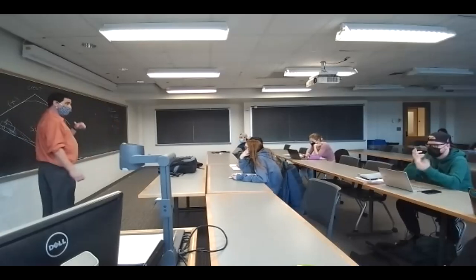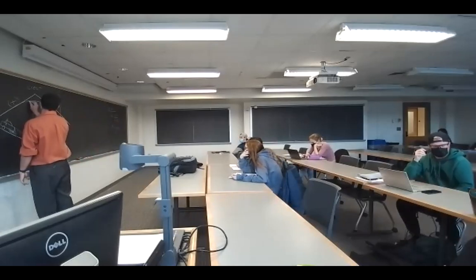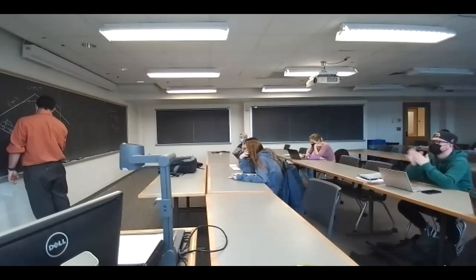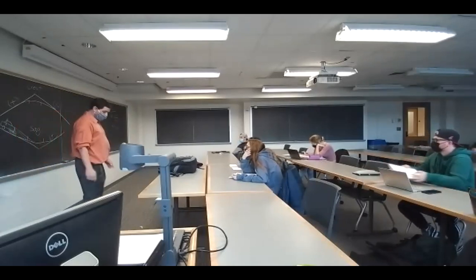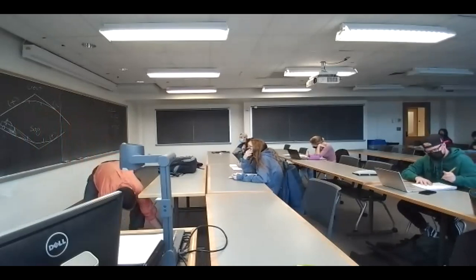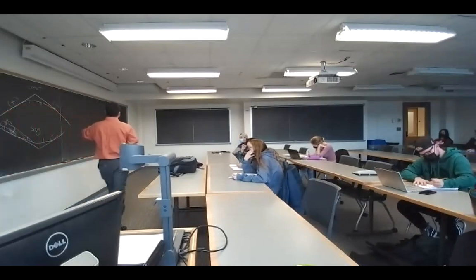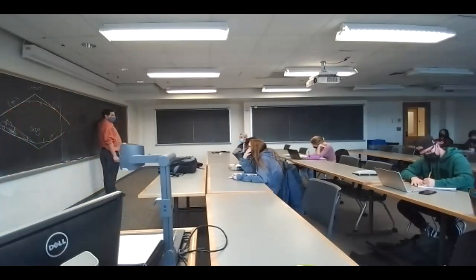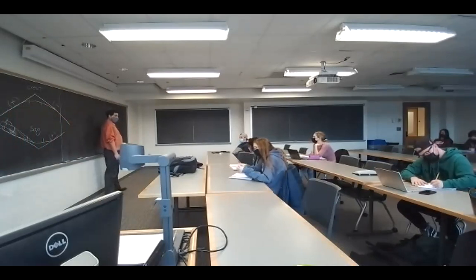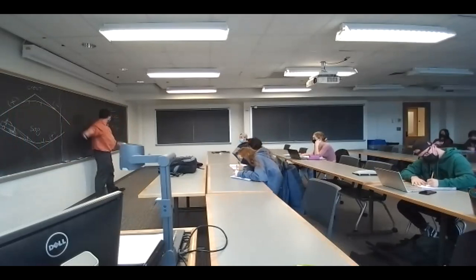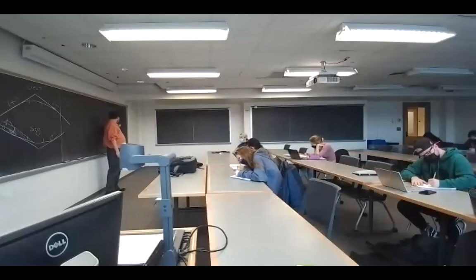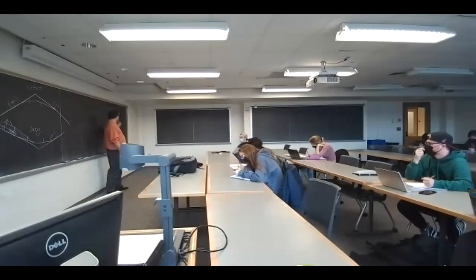If going in and going out are different, the high point can be one way or the other, or the low point can be slightly one way or the other. The way you calculate the horizontal position of a high point or a low point is with one of these two equations. If you're given the grades going in and out and you have the length of the curve, there it is. If you're just given one of the grades, but you know the rate of change, that's the other.